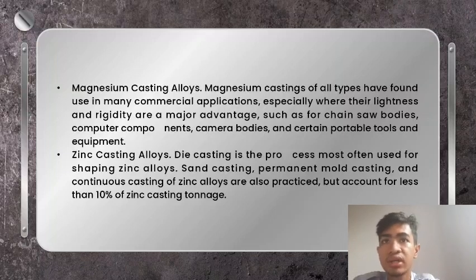Copper casting alloys. Copper casting alloys are available as sand, continuous, centrifugal, permanent mold, and some die castings. They are generally similar to their wrought counterparts, but have their own unique compositional or property characteristics. For example, the ability to add up to 25 wt% lead, which would not be possible for wrought alloys, provides compositions in which dispersion of lead particles helps prevent galling in bearing applications. Copper casting alloys are used for their corrosion resistance and their high thermal and electrical conductivity.